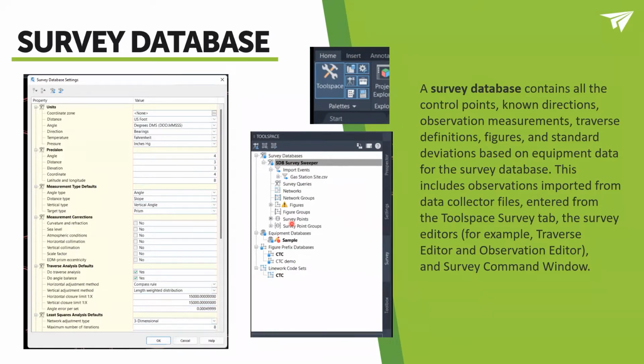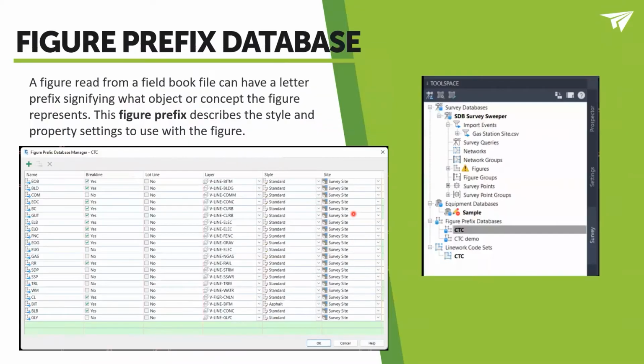Now, regarding survey figures and the difference between figures and codes: once our guys in the field shoot concrete, dirt, etc., they will put a code into our collector, and when we get that code into CAD, it is going to look at our codes to determine how they are going to be processed, if they're going to be linework, etc. Here are a couple of screenshots of how that is set up.